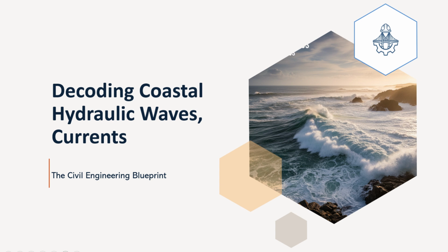Okay, so the dispersion equation is our master key because it unveils why waves of different periods, say short, choppy wind waves versus long, smooth swell travel at vastly different speeds in the ocean, especially in deeper water. This frequency dispersion is absolutely fundamental to how waves evolve, how they spread out from a storm source, and what kind of energy they ultimately deliver to your coastline. It's like different notes in a musical chord traveling at different speeds through the air.